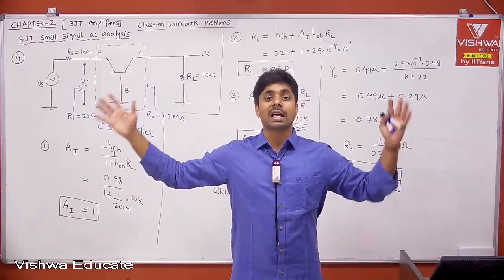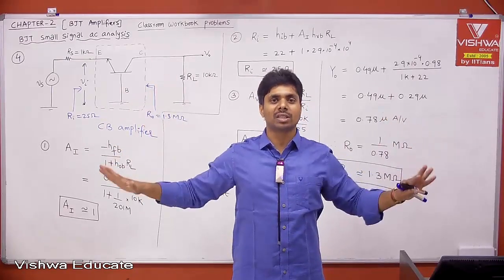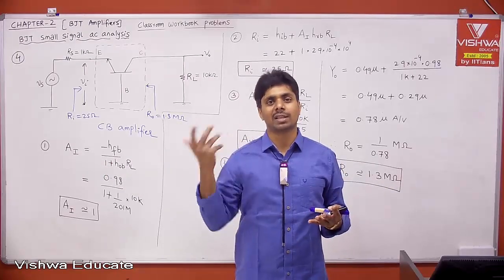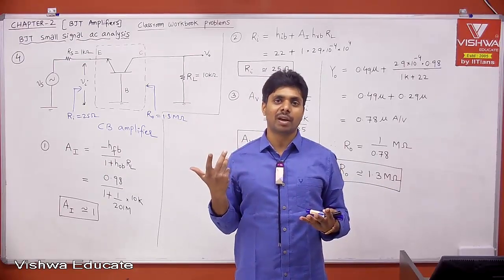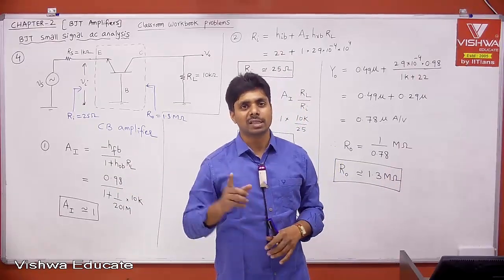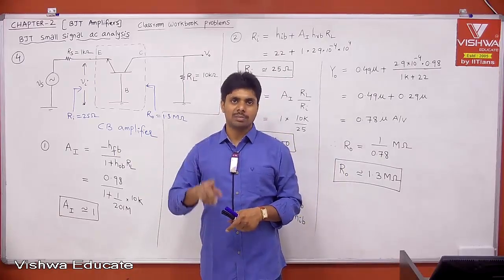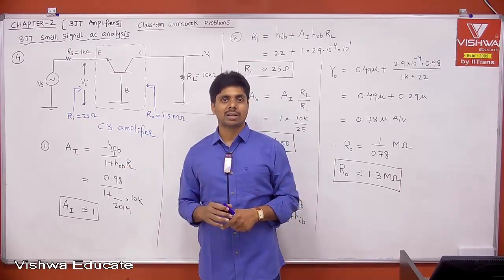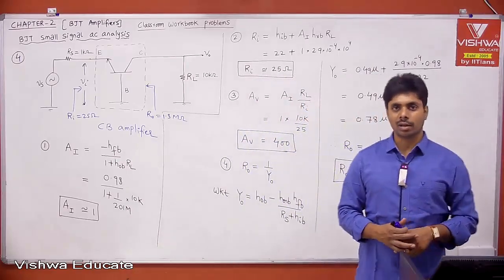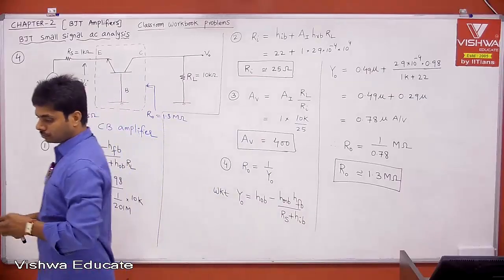Then it will be an overall current amplifier providing impedance matching for current amplification using CB amplifiers and providing current gain from the CE amplifier. I hope this is clear. It is similar to your CC, CE, CC, but that is a voltage amplifier. Now this is a current amplifier. Write down the conclusion, then I'll give you the block diagram. With that, the session will be over.